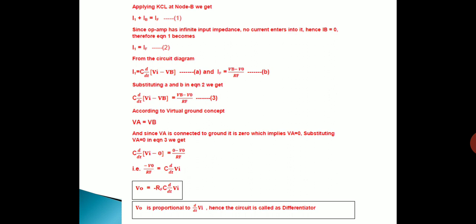Just a quick review of how we can do the derivation. You have to apply KCL at node B. You will get I1 plus IB equal to IF. Op amp has infinite input impedance, no current enters, so I1 equal to IF. Write I1, the current through the capacitor, which is given by C into d by dt of Vi minus Vb, and write IF, the current through the resistor Rf, which is given by Vb minus V0 by Rf.